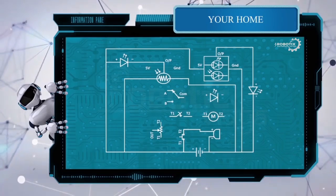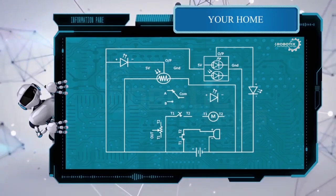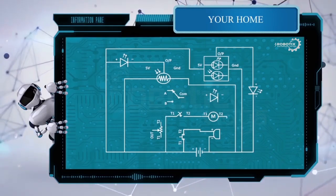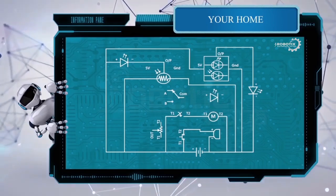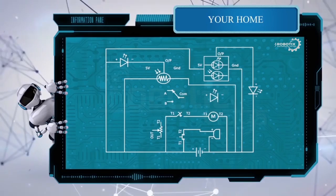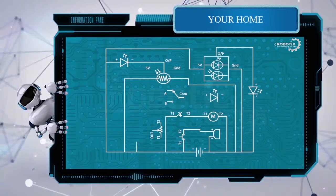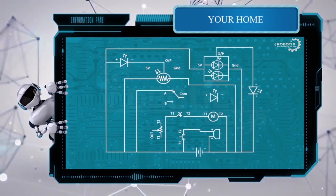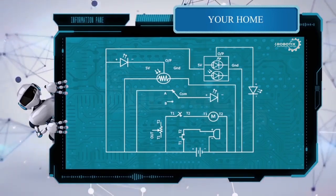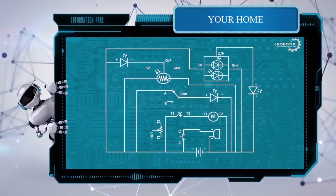So now connect the positive of your battery to the T1 of your push button and the T2 will be connected to your motor and the other terminal of the motor will come back to the negative of your battery. The next is your SPDT switch, that is a two-way switch. So connect the positive of your battery to the terminal A of your two-way switch and the common is connected to the LED positive and the LED negative will be coming back to the battery's negative.